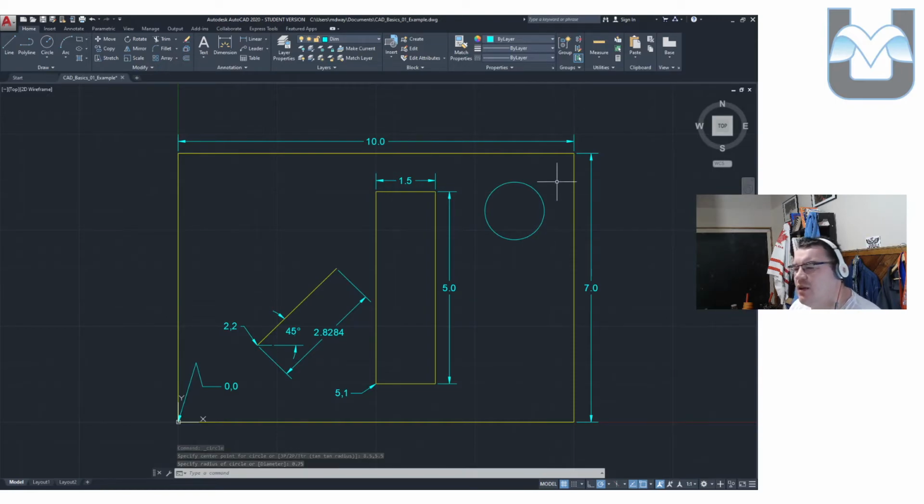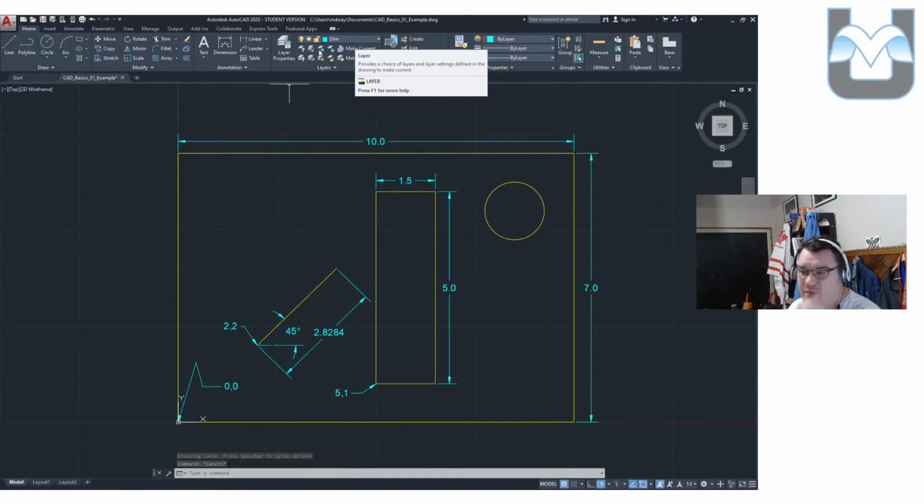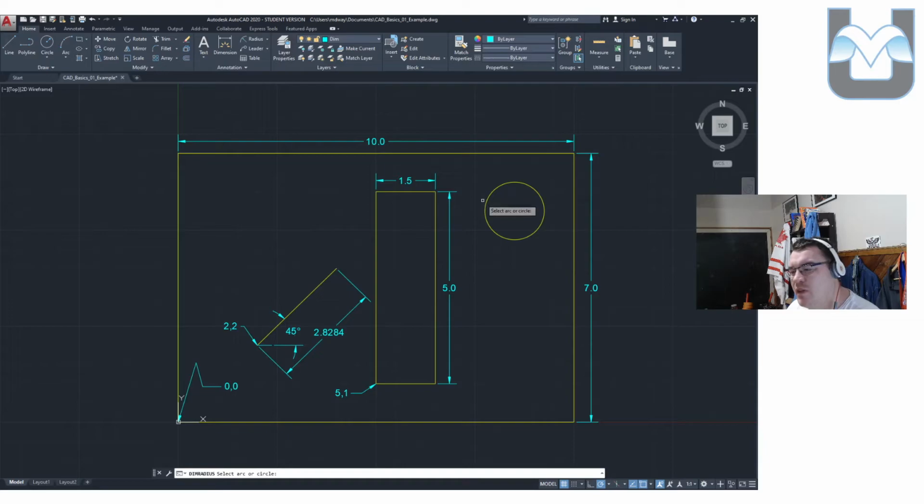That sucks. I'm actually going to go select this, and you'll notice I'm selecting from right to left. I get this little green lasso here. And I'll talk about that in a second. We're going to actually go and change its layer by just clicking on this menu and moving it into the correct layer. When I press escape to go back to normal, you'll actually see that it kind of goes back to whatever my layer was beforehand. And so I actually want a dimension right now, so it's kind of a good thing, but just be aware of that. And jump that up to 7.5.